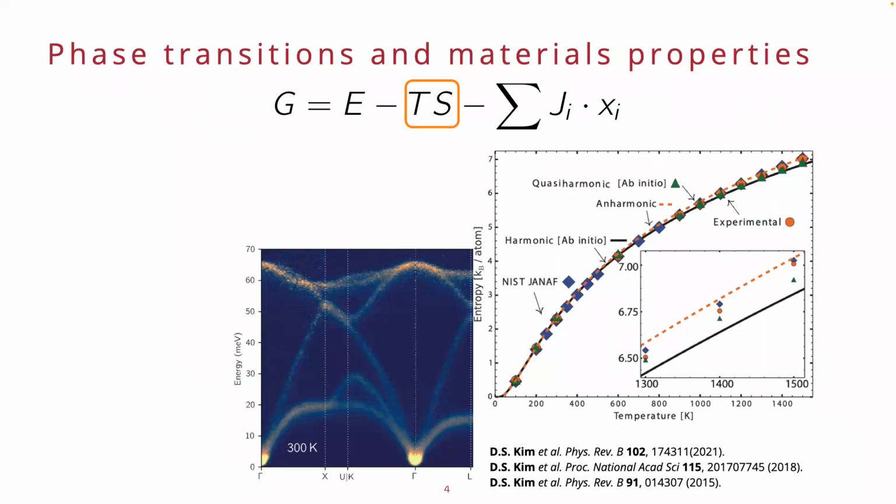One thing that's interesting is that because these are all chemical vapor deposited, you don't have a very uniform doping level, or it's difficult to control. So even in areas where we see one isolated rhenium dopant, we do see a very strong distortion. So in 2D materials, the doping concentration value is a little bit different because you're on such small length scales as compared to having a block of silicon, I guess, but you're right. That's a good point.